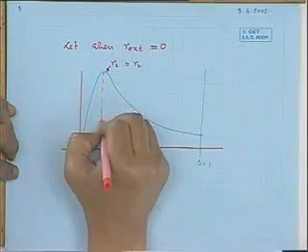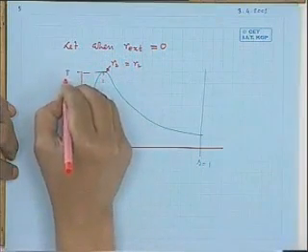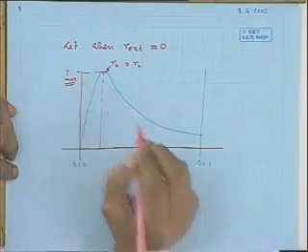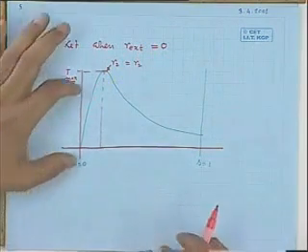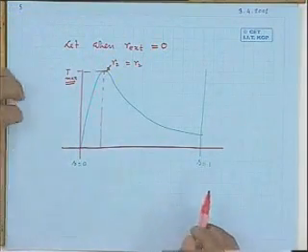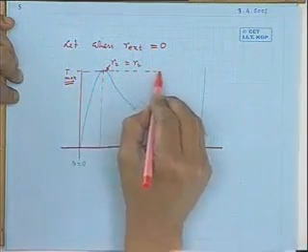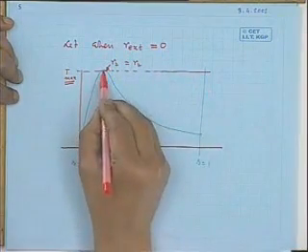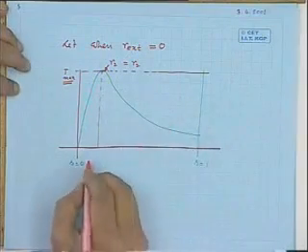Now suppose the rotor resistance per phase is increased, and this is the value of the maximum torque, T max. Do you think this maximum torque, wherever it occurs, will change? No, because it is independent of rotor resistance. So I draw a line here, and I know that the maximum torque point will lie somewhere along it.